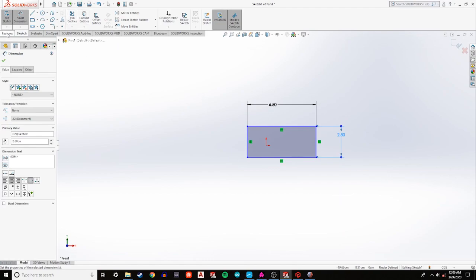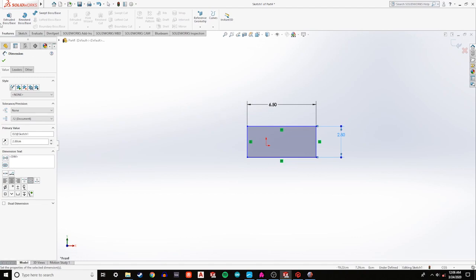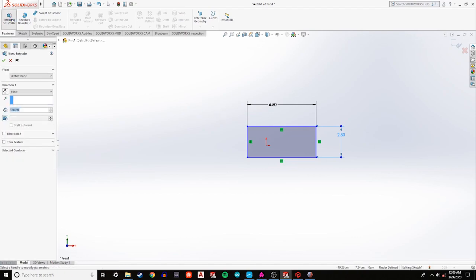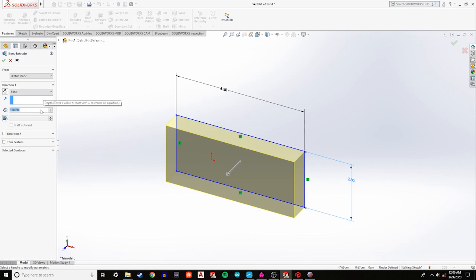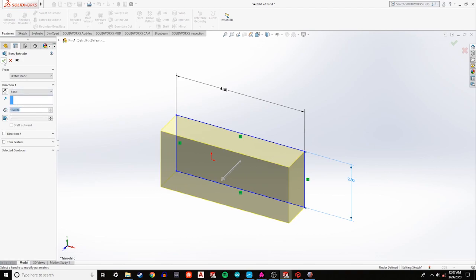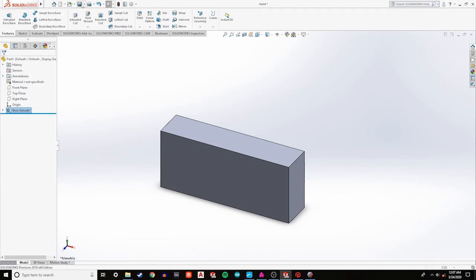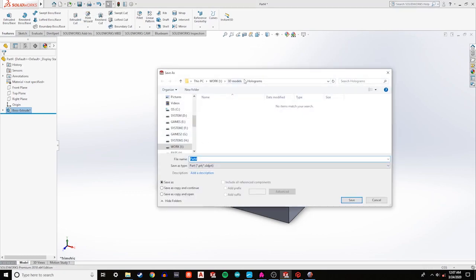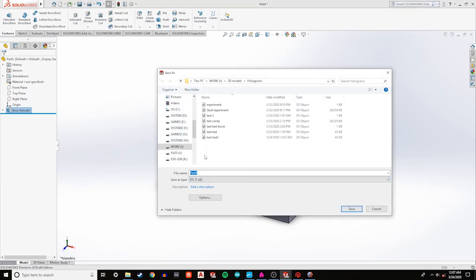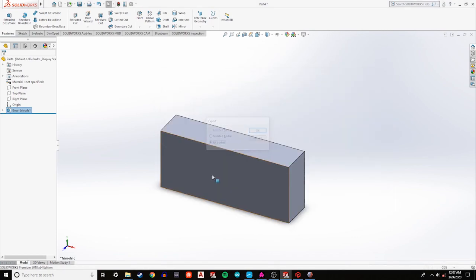And we know that I extruded the text to be 1 centimeter thick, and so we're going to make this just a little bit more than that. Go ahead and make it 15 millimeters this time. There we go. And now we have our box. And we can go ahead and save that as an STL. And this is my block right here. I'll just go ahead and make another one. And now we've got that.